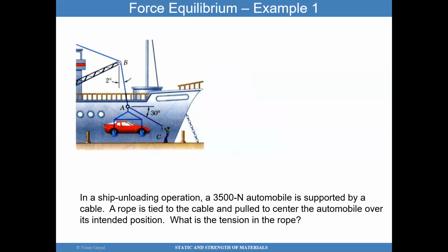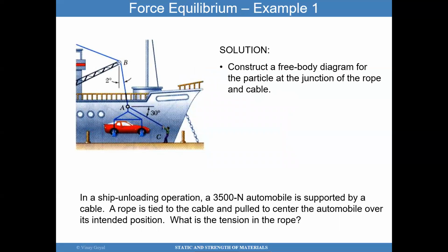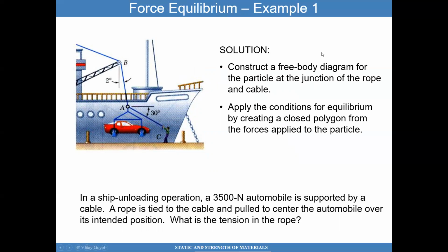So to solve this problem, what we want to do is to construct a free body diagram for the particle at the junction of the rope and the cable. So this junction here, we want to really understand a free body diagram for that area. Then we want to apply the conditions for equilibrium and solve the problem.